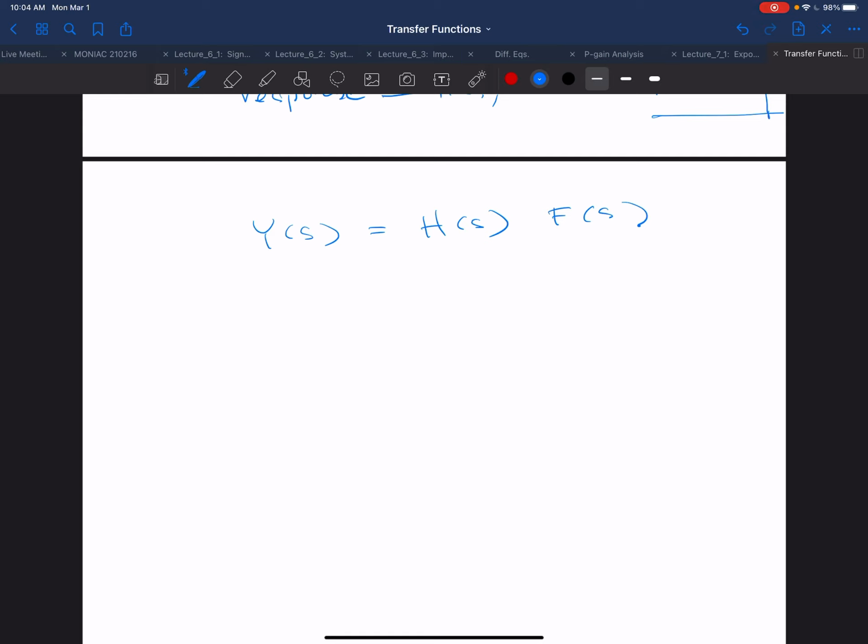But to find the response in the time domain, we're essentially going to consider a couple of simple input signals. In principle, the response of a system is completely characterized by its response to unit impulses, but unit impulses are not always the easiest signal to generate in reality, in the lab or on a test bench.